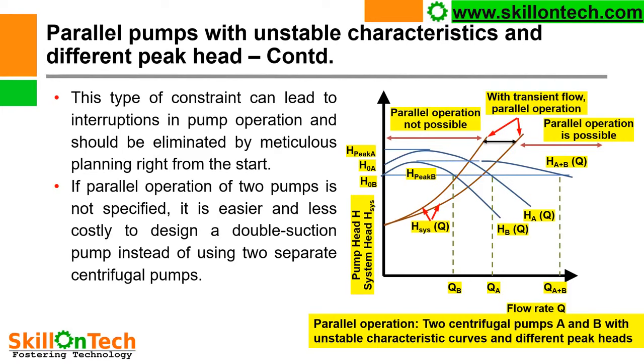If parallel operation of two pumps is not specified, it is easier and less costly to design a double suction pump instead of using two separate centrifugal pumps to meet the process flow requirements.